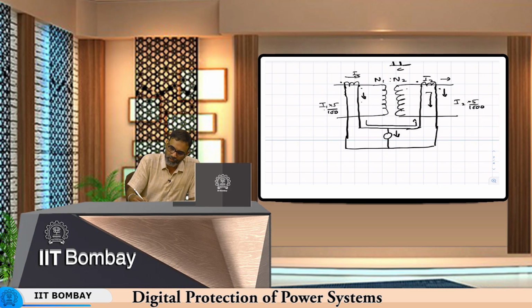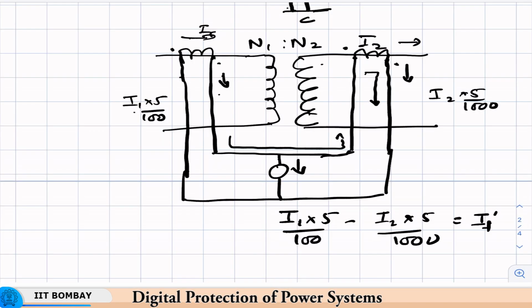So there will be a difference current here which flows through this path. I1 into 5 by 100 minus I2 into 5 by 1000 is equal to some current which will be flowing through this path. Now, if I put a very sensitive current relay here, then even for very small currents, this current is known as a spill current because it spills over from the main path. So this spill current will operate this sensitive relay, and I can obtain a fault indication or a trip. So this is the principle on which a transformer protection differential relay works.